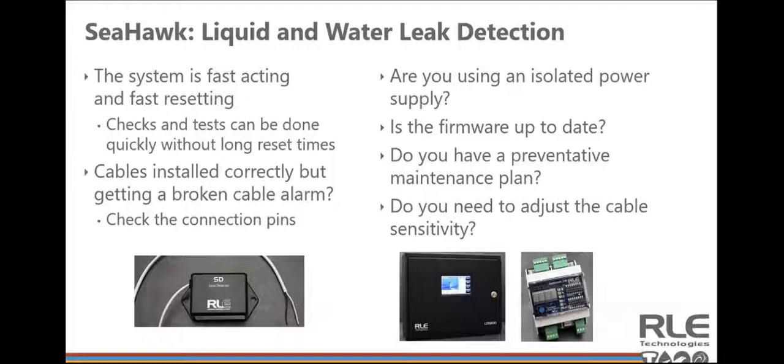As Brian said earlier, you're going to want to use an isolated power supply first. That, as he said, is where we have found a lot of problems. Another tip: perform maintenance. I know it sounds basic, but that is a big thing.